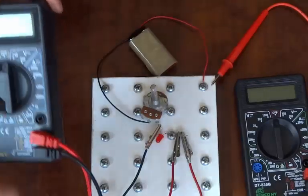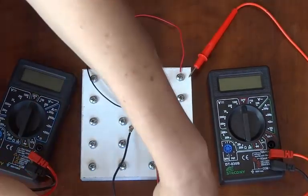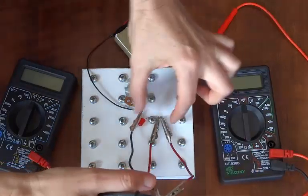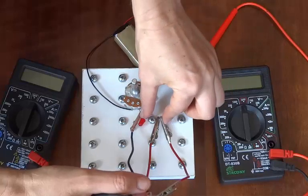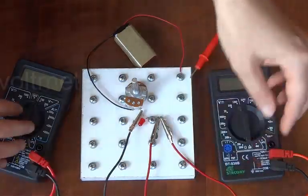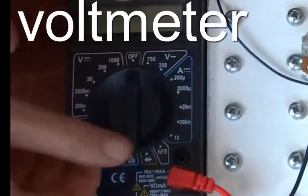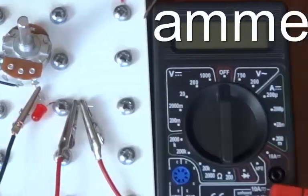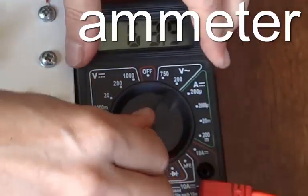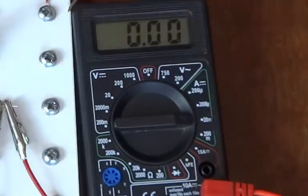So this one is a voltmeter, and you can see its probes are connected there across the LED, not across the variable resistor, across the LED. So this one's a voltmeter, this one's an ammeter, so we must turn this one to the voltage 20 maximum range, and this multimeter we must turn to the current strength maximum 20 milliamperes range, and then we close the circuit.